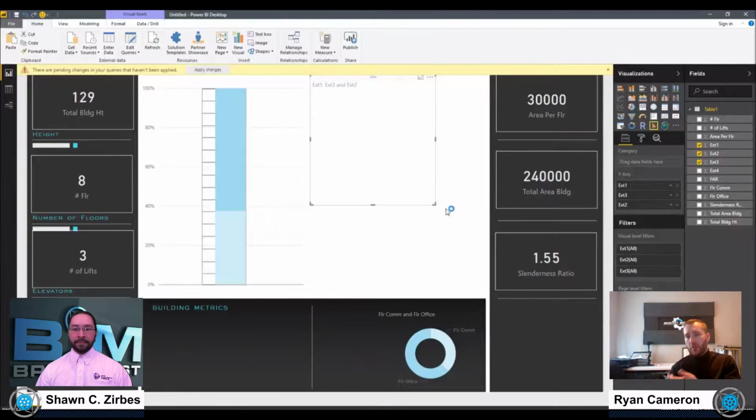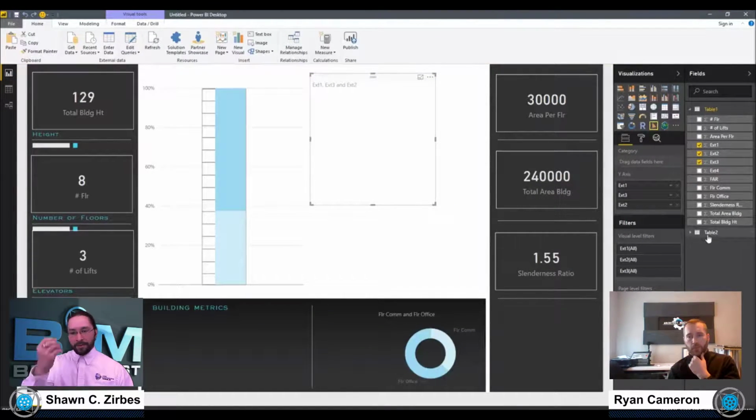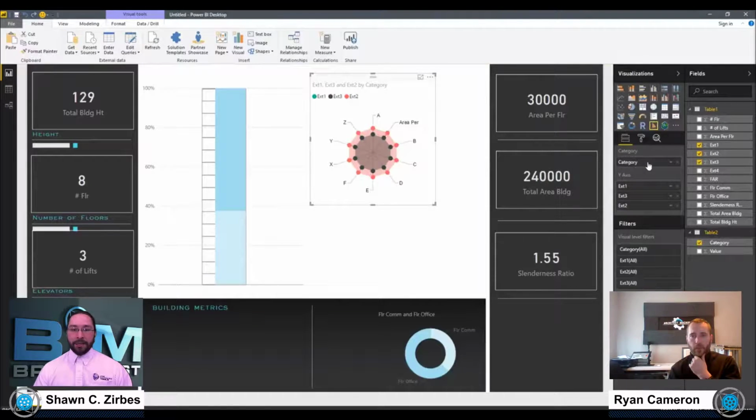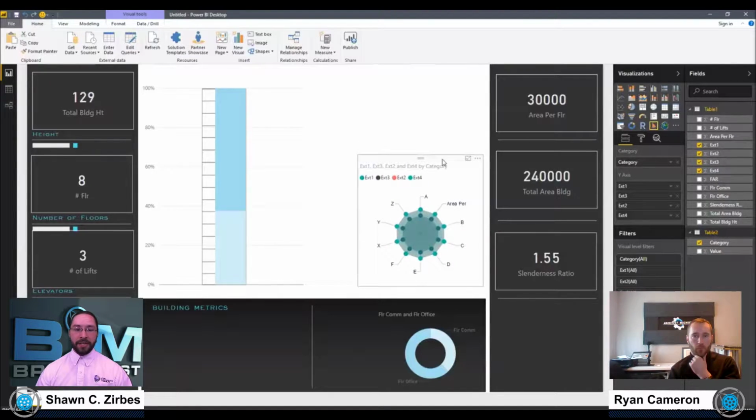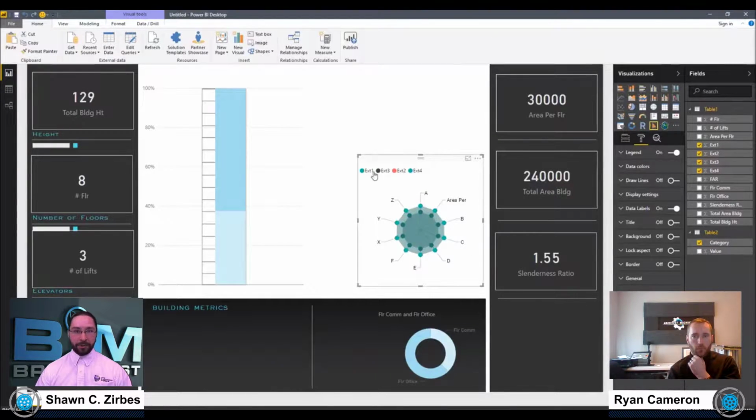And I could rename the table to be radar chart value something. Yeah, just being generic for the sake of a demo. And in this case, the radar chart isn't looking incredibly interesting because you just copied and pasted those values down, but it gets much more interesting when you're actually taking specific levels, specific areas, and getting their real data plugged into this from, say, a Revit export or something.